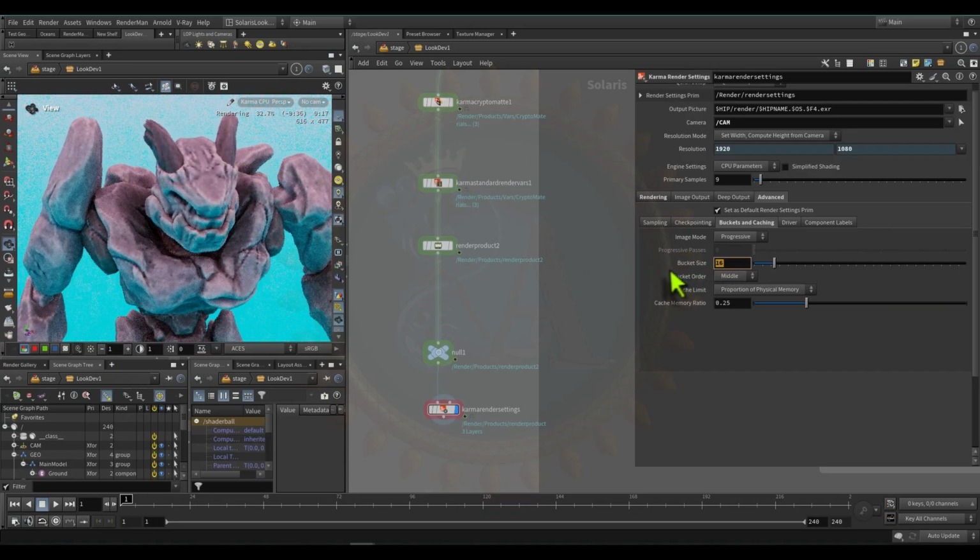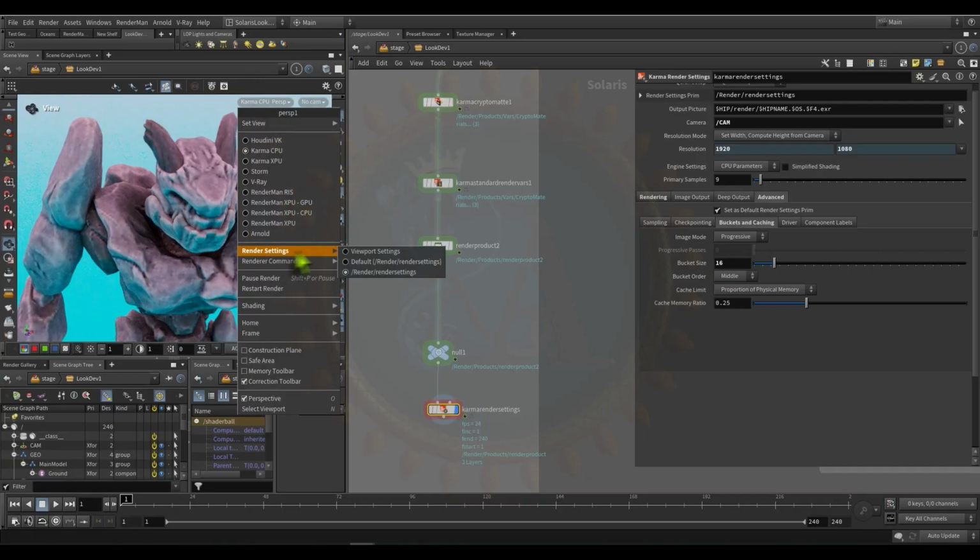Okay, this you may get confused. Whatever number of cores your PC has, those cores will be taken to this count. So more cores will make the render much faster. And also if you have a big bucket size, that one bucket will be this big, for example. So until this area is rendered, that core, the bucket, will not move to the next area. So if we make small pieces, automatically once that is done, that bucket will move. You can see the render speed now.